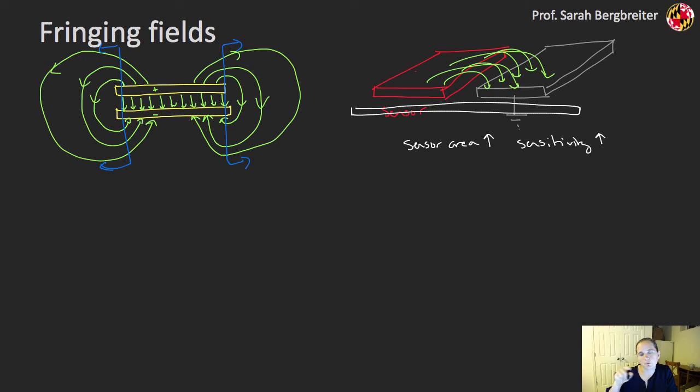Right, and this is really working by, as I'm moving my hand or some other substance, maybe it's a fluid or something, over this, as either that dielectric constant around these two electrodes is changing, or as I'm providing another ground path, say my finger over this, I'm actually measuring then a change of capacitance at that sensor. Right, I'm changing the overall capacitance of this system.